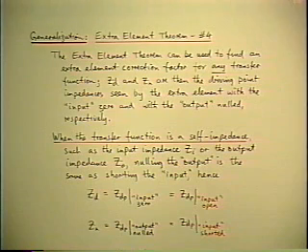Well, where we are right now is we've done another extension of the extra element theorem, which is just a reminder, basically, that it can be applied to any transfer function. It's simply a matter of identifying properly what is the independent input and what is the dependent output for the transfer function that you wish to correct by using the theorem.